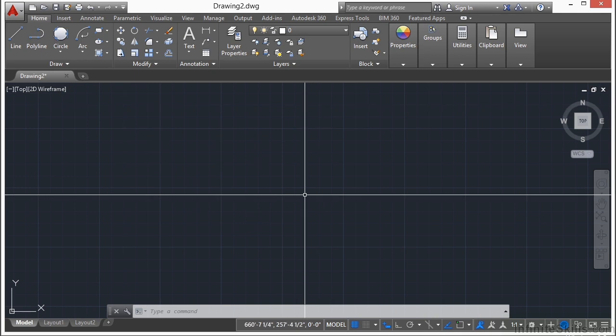In an earlier section, we discussed how AutoCAD uses a Cartesian coordinate system. Now, sometimes we need to create nodes at specific coordinates. Now, those are known as points. There is a command that can help you draw a point. Now, its size doesn't matter because a point actually has no size. It's only a marker or a node for a specific set of coordinates.